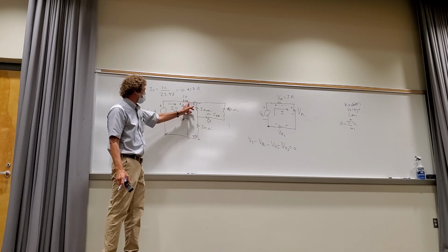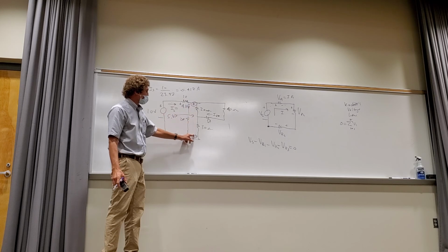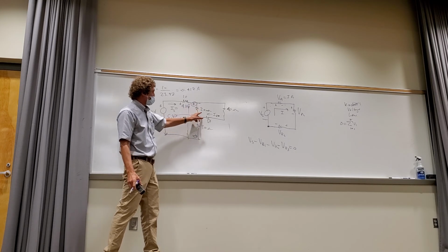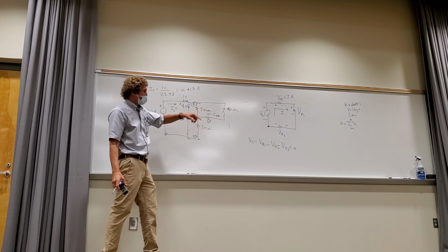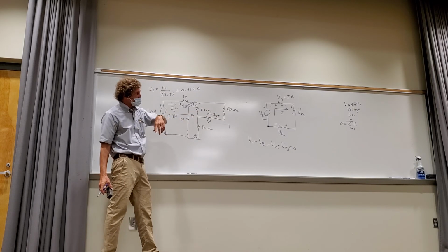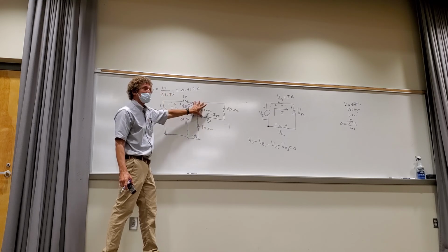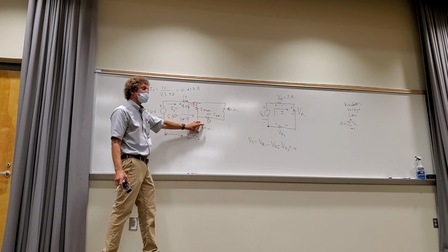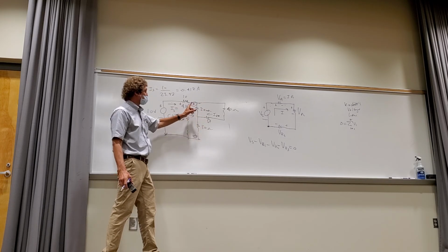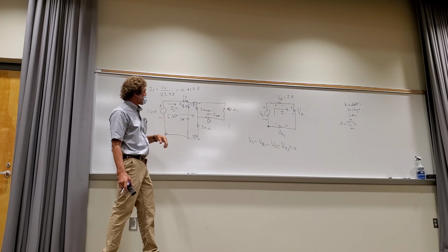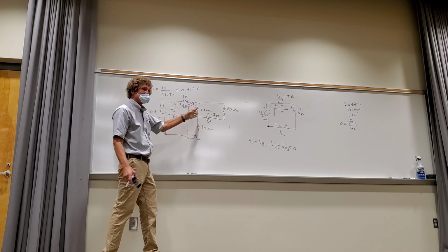Y'all agree if I have this many volts from here to here, I could say that that 20 was in parallel with 90, and that was equal to, I forgot what it was, 13 point something? You did that before. 16.3. We had an equivalent value of resistance here, right? Y'all remember that? I could take that equivalent and add 30 to it, right? And then I could divide that by what? Divide that into 4.17 to get, sorry. Or wouldn't you have the 20 in parallel too? Yeah, but I'm just worried about the current coming down here.